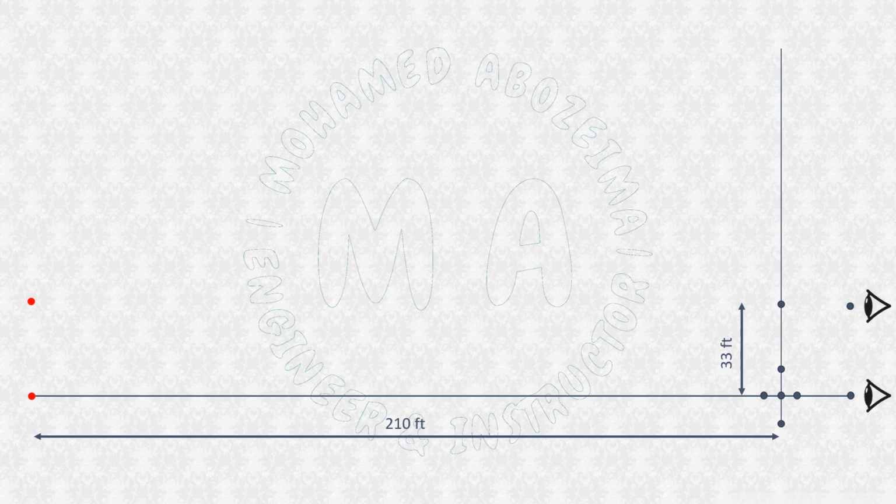The tanks have a constant width, which equals 8 feet, and at least 8 feet of safe distance from the waste pit should be available. So we will add to the 33 feet measured before another 8 feet to mark the mud system and another 8 feet to mark the waste pit.